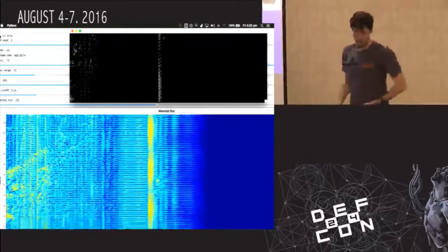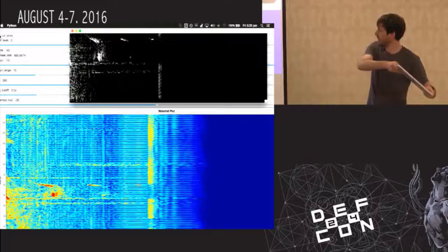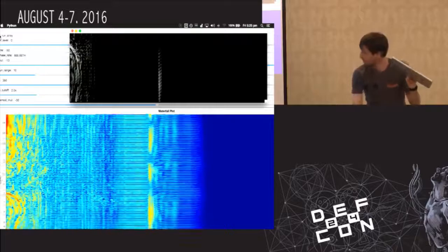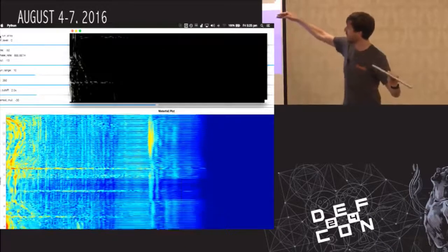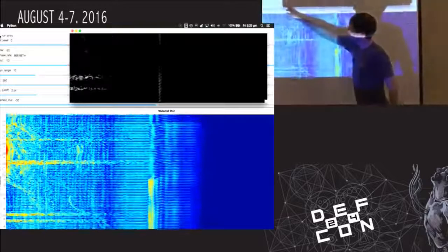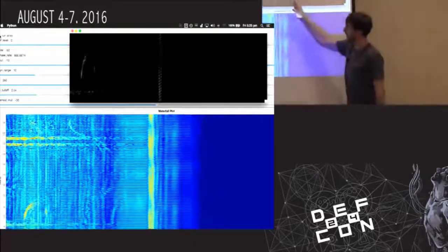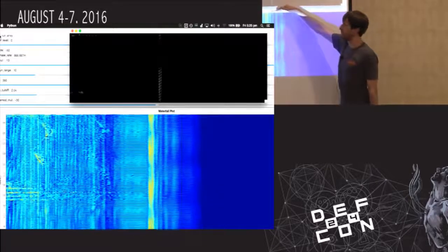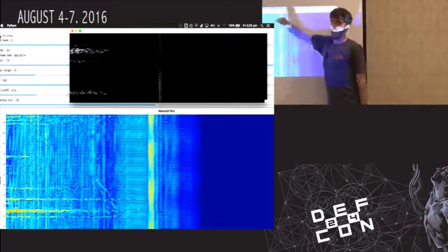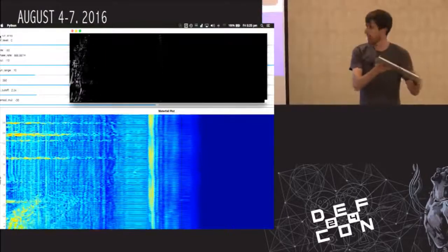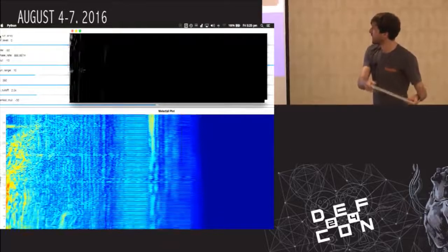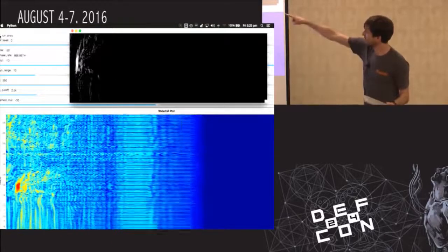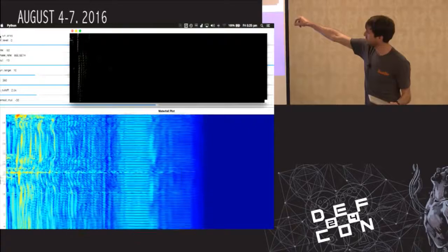beamforming range. So the idea is that if you were to hold it here, say, you've got to sort of get it right. It's very, very finicky. But the idea is that you would see, on the horizontal axis, the x-axis, this is still range information, but your vertical axis is now angle information. So you would expect to see sort of a hot spot at the angle at which your target object is actually sitting. And again, maybe the transfer function isn't quite right, but oh, there we go. Yeah, see there? Was that a fluke?